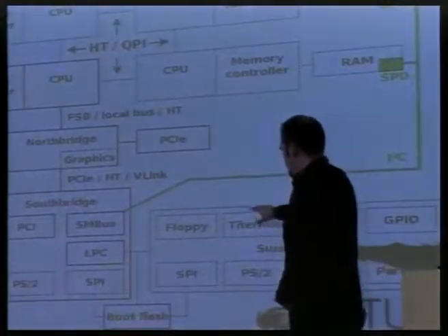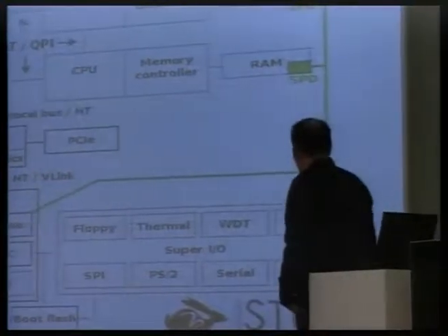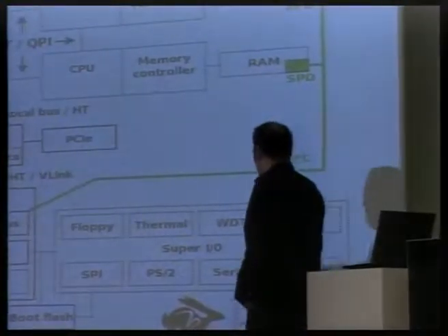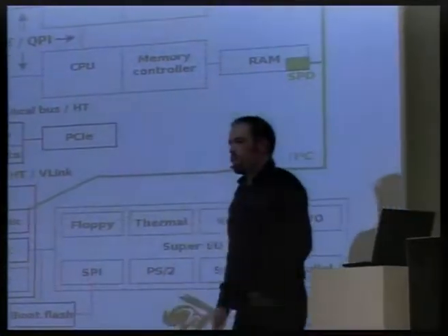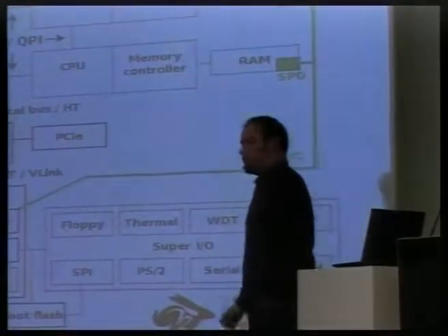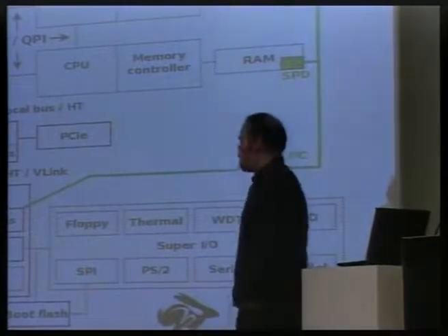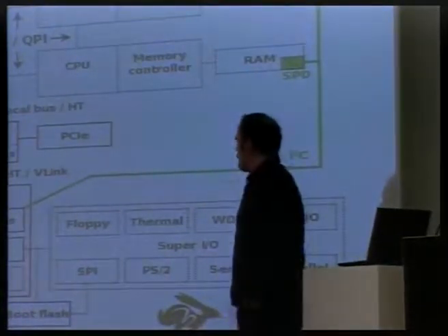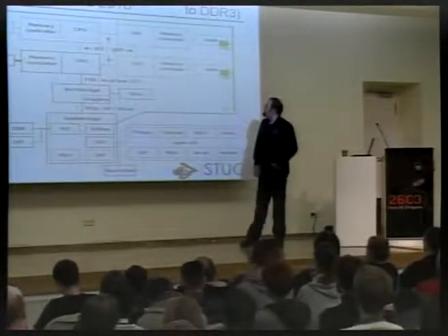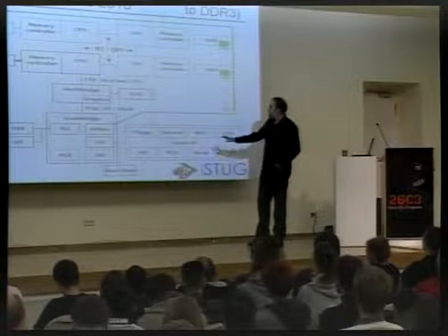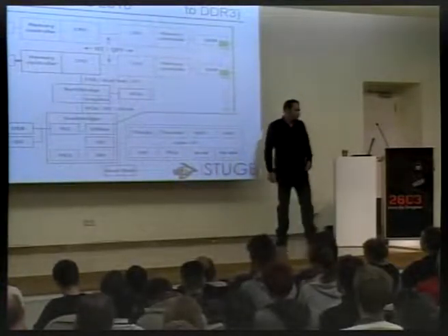Super I/O, most of these functions, let's see, serial, parallel, watchdog, maybe GPIO, and the floppy drive anyway, they have I/O ports that need to be set up, and they have interrupts that need to be set up, and they might even have a DMA configuration that is necessary to be programmed elsewhere in the system so that whenever something happens over here, the CPU will actually notice. So that's the coreboot task.